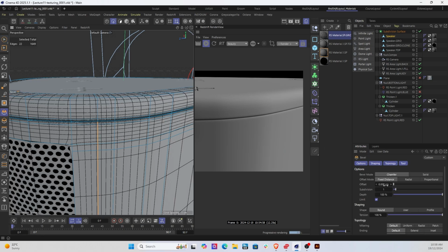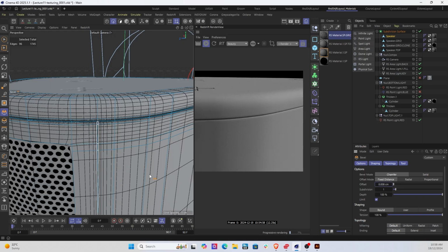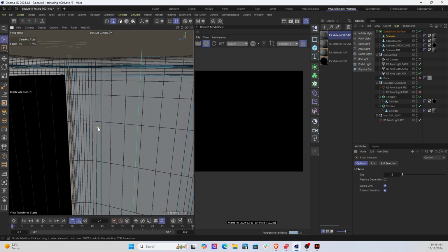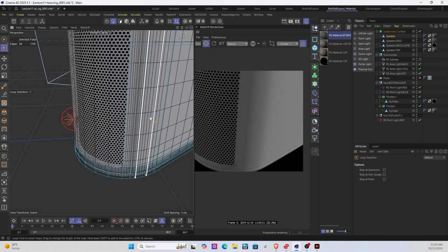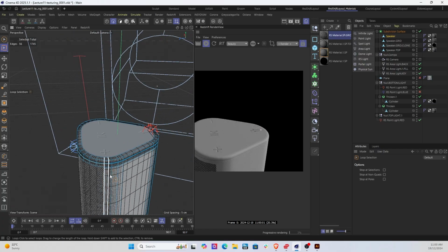And there it is. So as soon as you've done that, it would have done that for you. And that's the bevel. So next we need to select the inner line of the bevel. Now, if we go ahead and click UL, what it will do is just connect all our lines. So if I go UL now, it's going to select our lines that we really don't want. Now you could click that and then just unselect the other lines that you don't want clicked.